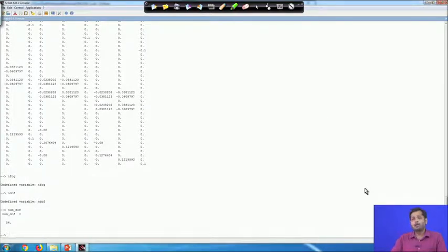But you can have a structure where the number of degrees of freedom is huge, in the thousands. In that case the size of the stiffness matrix will be 1000 by 1000. In a real structure it is much more than that. But if you look at the stiffness matrix, most of the entities are 0. Depending on the connectivity of the members, only some elements of the stiffness matrix will be non-zero. So storing that stiffness information is an important part of the code. One very crude way is to store stiffness in matrix form.